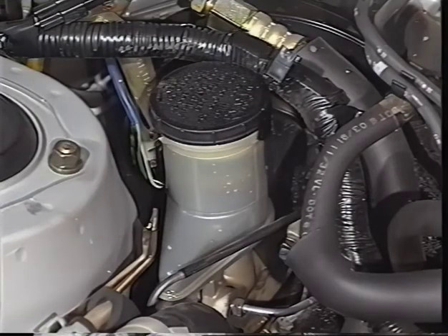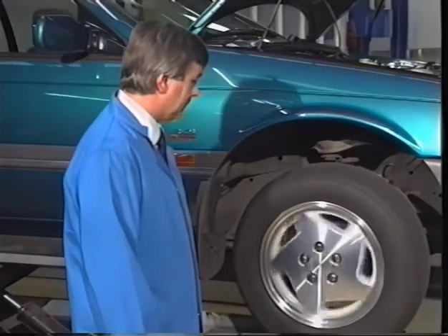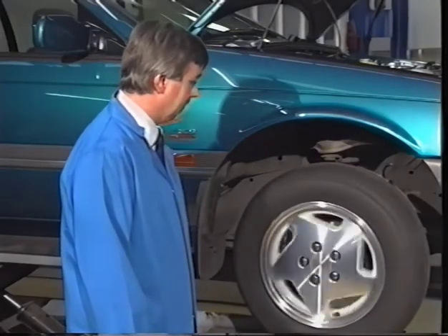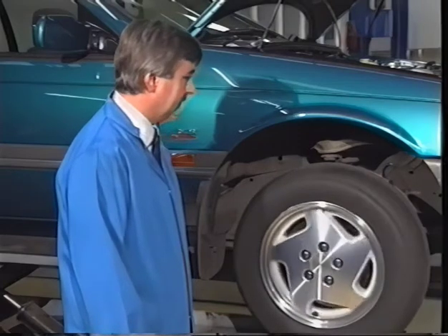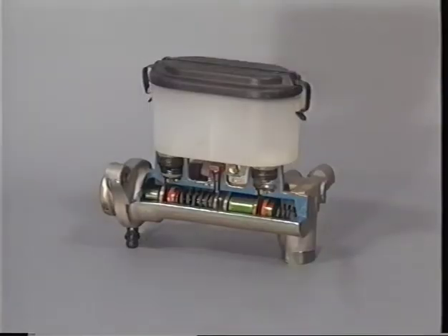The final test in this path is the master cylinder itself. In the interests of fuel economy, modern braking systems run greater clearances between the pads and disc rotors, giving far less drag than earlier systems. This has resulted in the master cylinder having to displace more fluid. To maintain correct pedal height and effort, the fast fill master cylinder has been introduced on many current vehicles.